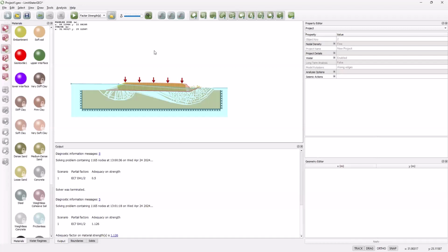I've got another question. Can the software model a Tri-X geogrid? I think essentially, if you're happy to represent that as I've basically put it in here, you're going to put in a rupture strength for it, and you can define upper and lower interface parameters. And yes, I don't know the specifics of that particular grid.